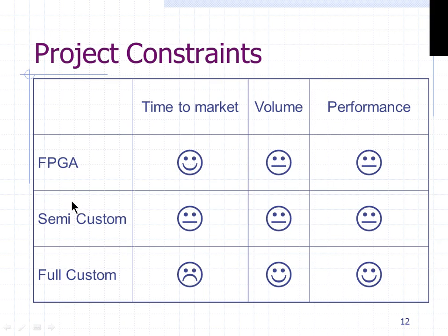So semi-custom IC design, nobody really does. Very few projects are done on a semi-custom ASIC nowadays. Either people go for full custom ASIC or they will transition to FPGA, the bigger size FPGAs, the latest FPGAs, which will give you almost everything that a semi-custom ASIC will give.